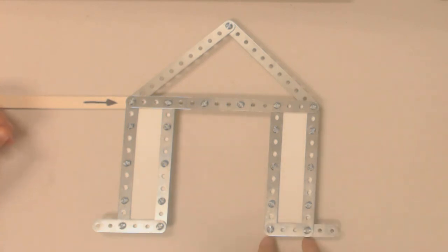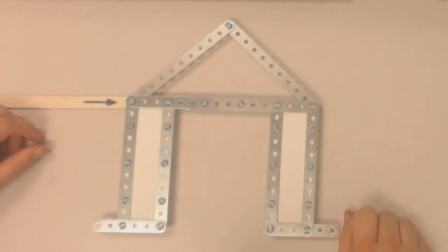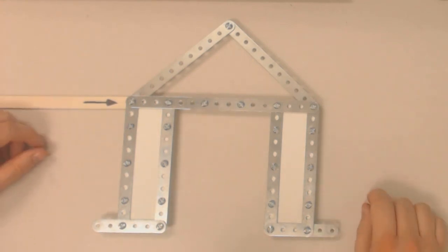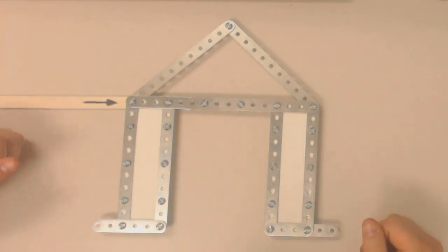If the anchors to the foundation are the weakest point, the building won't stay where it's supposed to. It'll move. The anchors will pull out of the concrete, or the foundation won't hold it. All of these different things have to be taken into account in the design and construction of a building, so that everything will work together to counteract the loads that are imposed on it.